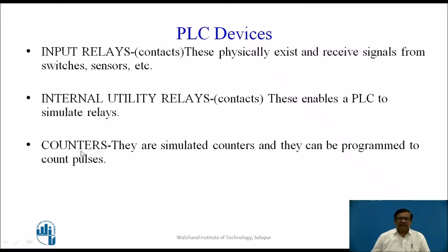Then counters. They are simulated counters and they can be programmed to count pulses. So actually these counters are also programmable, which can count the number of pulses, and based on the number of pulses counted, the contacts can be made on or off.